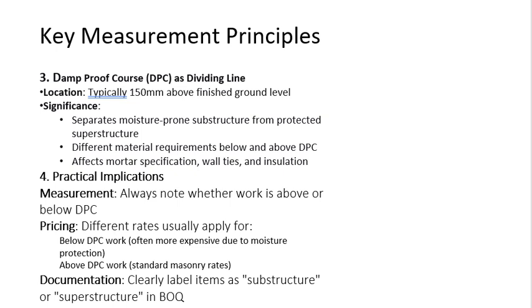Mortar is what you use to join the blocks. If you have seen wall construction, they will put the block, then they will put some material on it, some light concrete which does not have aggregates. That is called mortar. So mortar is used for joining the blocks in the wall. It acts as a joining, binding material. Based upon your DPC, your mortar specification can change. The ratio of sand and cement and water can change.